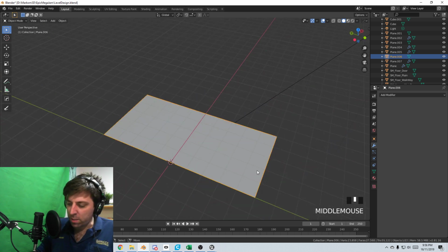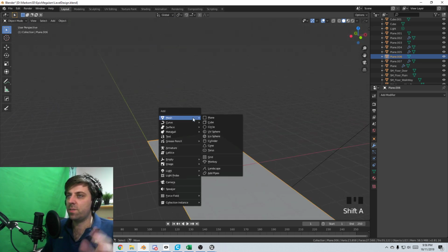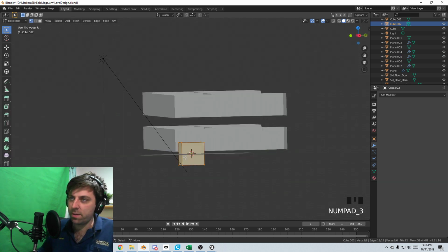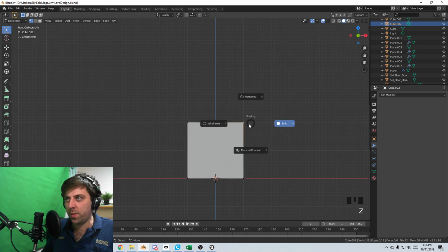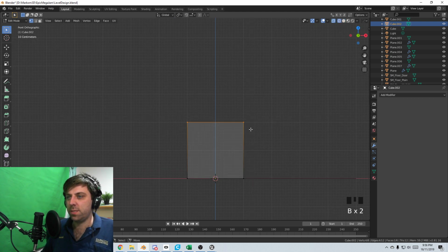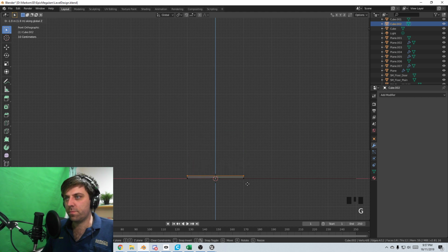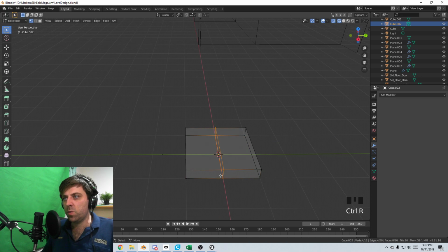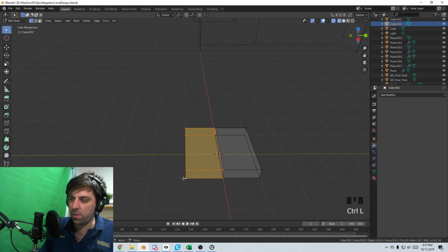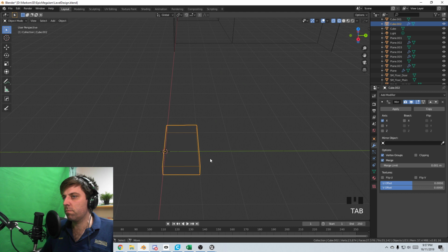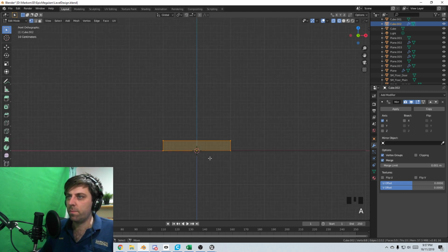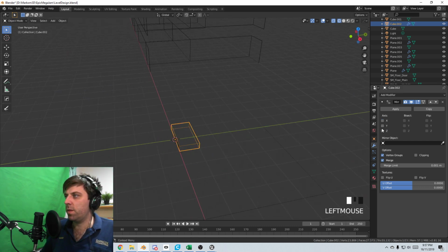And I do like the angle effect, but then that just adds an extra layer. Oh my goodness, the complexity. Okay, let's just make a chair first. You know what? Let's just have a break. Let's make a chair. GZ, so that's 2 meters high. That's a big chair. Let's bring it down. Let's just start off with a cushion. Let's put that in the middle. V to rip. Ctrl L, delete. Mirror modifier. On the Y.